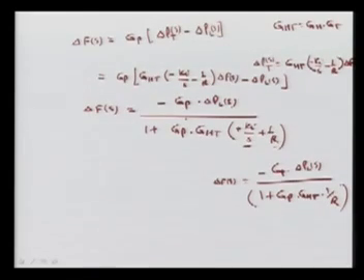So for this, what we can do, this change in Fss, again we can use the final value theorem, and that is nothing but the limit S tends to 0, and here S into change in Fs, means first we have to put S and then you have to put the value S equal to 0, and then you can get it.